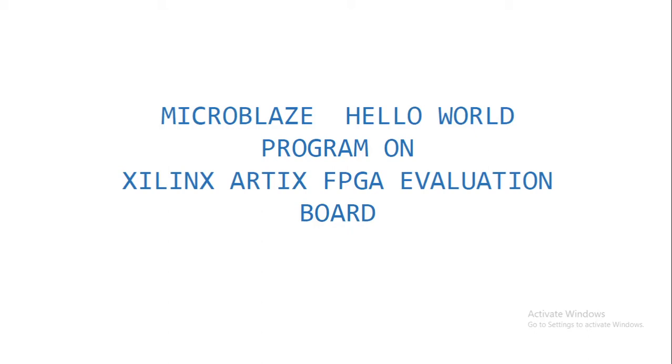In this demo, I'll be showing you how to create a MicroBlaze processor-based design on an Artix FPGA from Xilinx. I'll also show how to create a simple C program for running on the MicroBlaze processor using the Xilinx SDK.